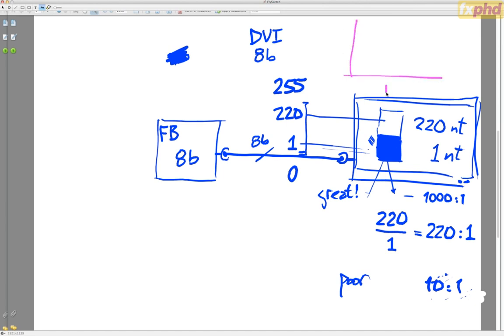The reason that it's not is that the display itself is taking those video numbers, which I always like to put on a scale of 0 to 1 because I'm a mathematician. But in terms of the integers on the wire, this might be 1 to 220 or 1 to 255. And the display is doing this power function that I keep fetching over and over and over.